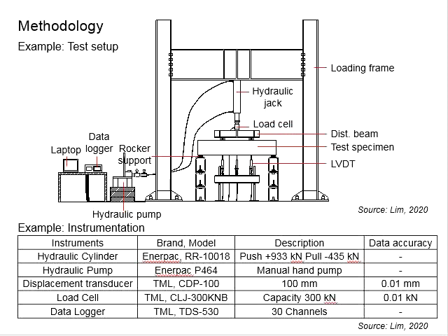Let's say now you found your design is okay, it is strong enough, but your testing is only meant for a specific effective length. Is it going to be the same when your effective length becomes longer? Or is it going to be the same when the beam is actually a continuous member and your simulated load is 2-point load with 2 supports? Your testing can only simulate 2-point load. In this case, you do not know whether the uniform distributed load or triangle distributed load may be applicable for this test specimen.